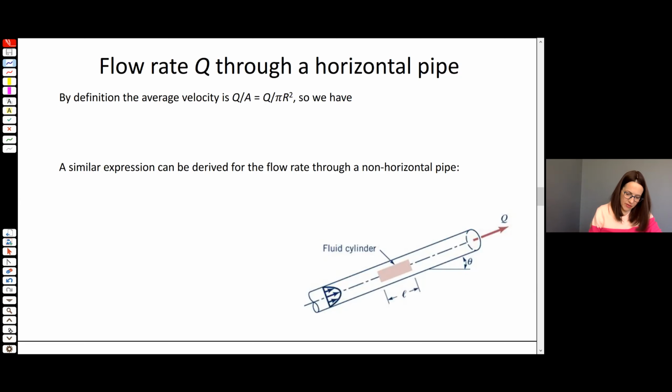So we have the average velocity V equal to pi radius squared centerline velocity over 2 pi radius squared, or it's equal to the centerline velocity over 2, right? So very important, the mean velocity, the average velocity in laminar pipe flow in this parabolic velocity profile is the centerline velocity divided by 2.